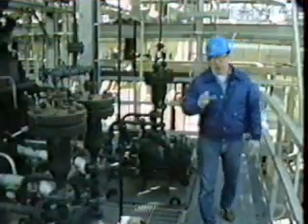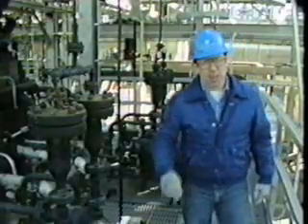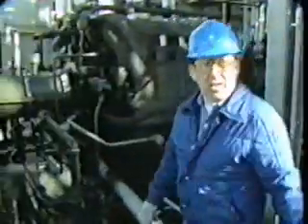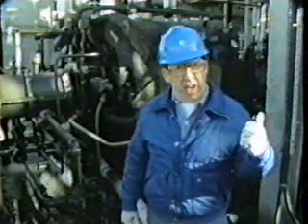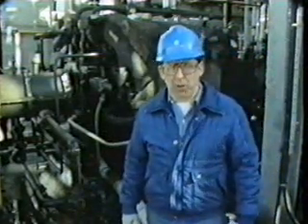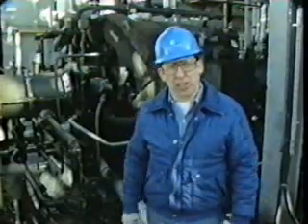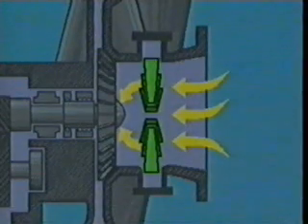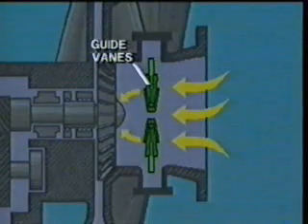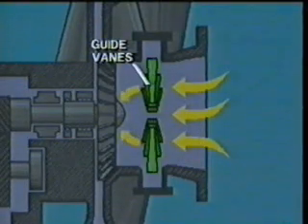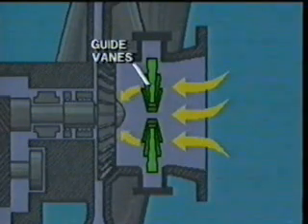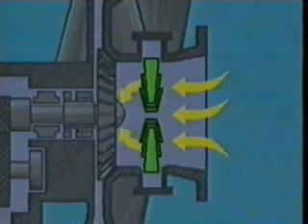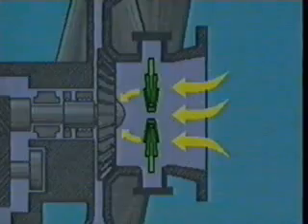There are several factors that affect performance of the compressor. For example, varying the speed of the compressor will vary the volume of gas moving through it. Recycling gas back to the suction side will also alter the performance characteristics of the compressor. So in this way, operators can achieve different results for the compressor. To control performance in some compressors, adjustable guide vanes are installed just ahead of the impeller. These guide vanes slightly throttle the suction gas flow and pre-rotate the gas into the impeller eye. These guide vanes can either be adjusted manually or adjusted automatically with a suction pressure controller.